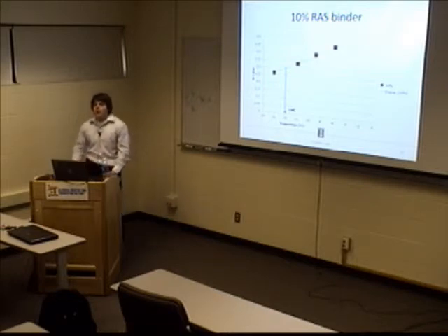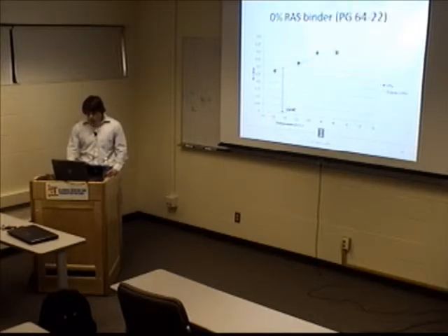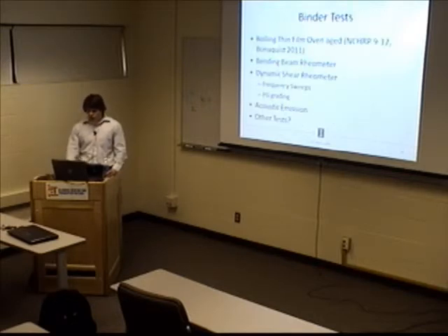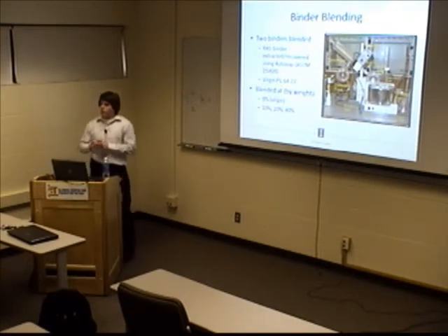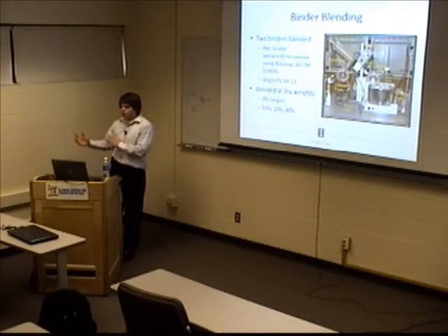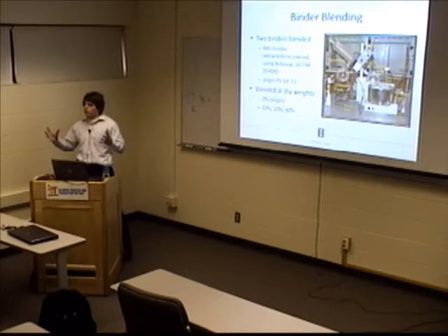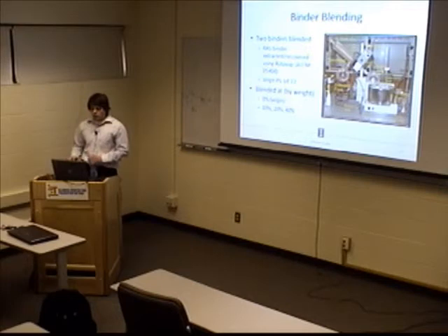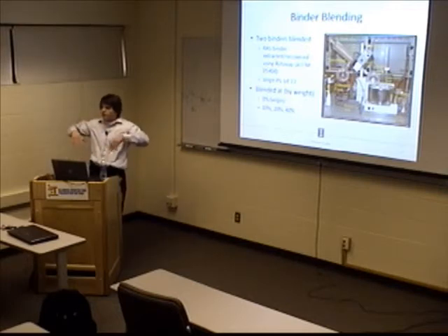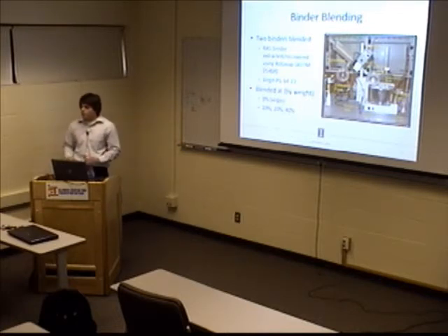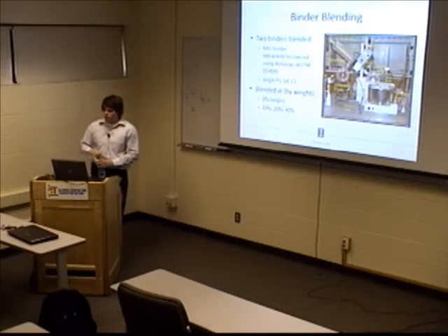I think at the surface, you're focused more on the performance grade. That's what the Superpave performance grade is for the most part. When we talk about surface mixtures, we're not concerned about any of the materials underneath. The only thing affecting it is the material itself, right? So the temperature value, the minus 2.4 or whatever you saw, that was at a depth of whatever your layer was, right?